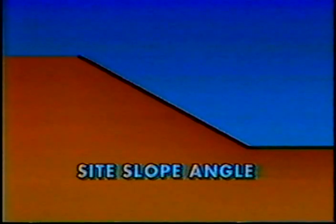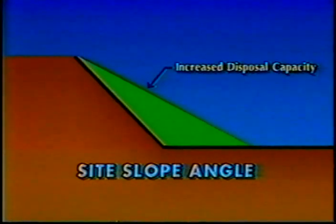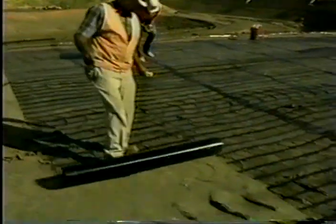Traditional landfills had shallow slopes to avoid the possibility of slope failure. If the slopes are reinforced with suitable geosynthetic materials, they can be made steeper to increase landfill capacity. Transverse geogrid layers placed at intervals can help stabilize the sides, again making a steeper slope possible. Soil reinforcement results from the strength of the geogrid and the interlocking between soil particles and grid apertures.